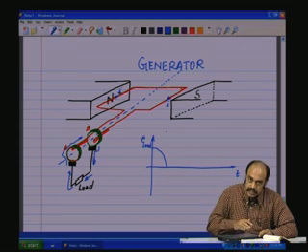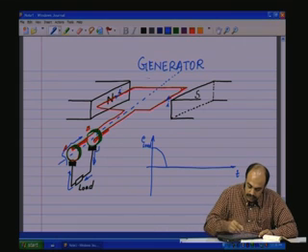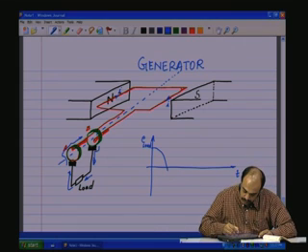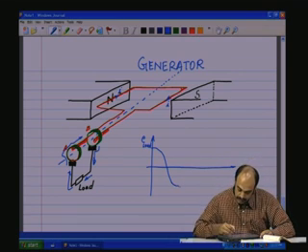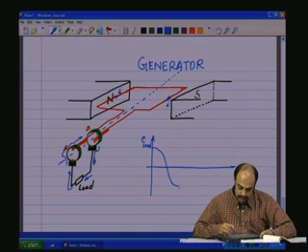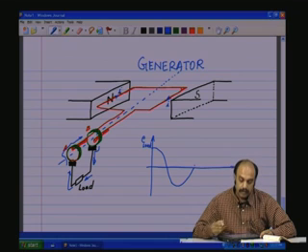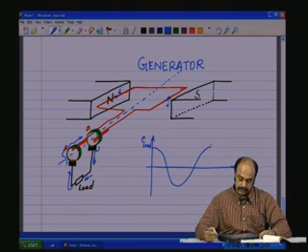And then when it starts again rotating further towards the south pole, that is this portion rotating towards the south pole, it starts going in the other direction, and then again when it becomes perpendicular to the existing direction, orthogonal direction, there is no flux, and then so on, it keeps going like this.